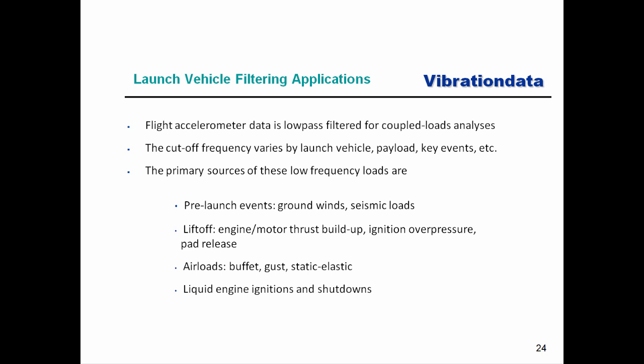And we're concerned about low frequency events or loads, and these could come from pre-launch events like ground winds or seismic loads. And again, you might think, well, earthquakes and launch vehicles, how do those fit together? Well, some of our launch vehicles go out of Vandenberg, California, and that's located near the San Andreas Fault. And that launch vehicle and its payload is like a big cantilever beam sticking up from the ground.